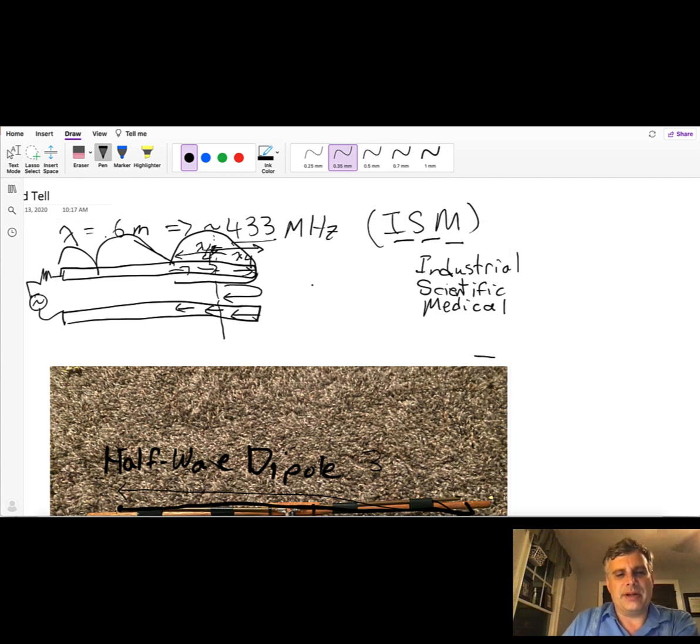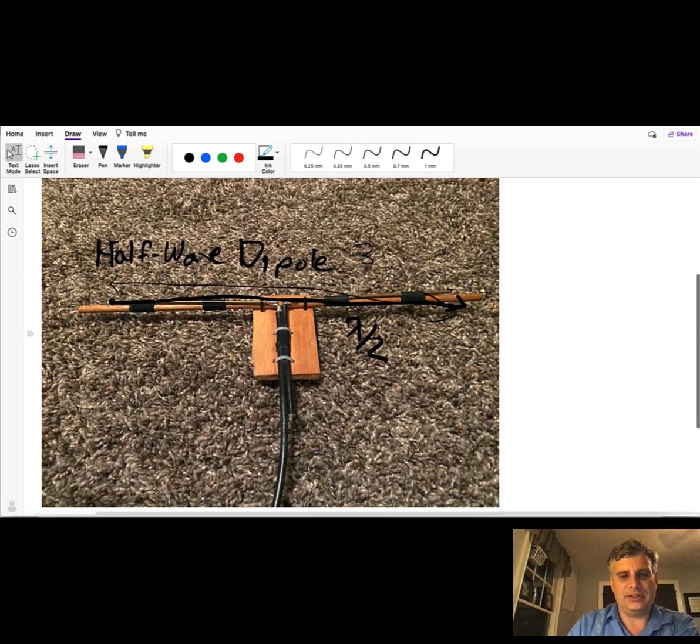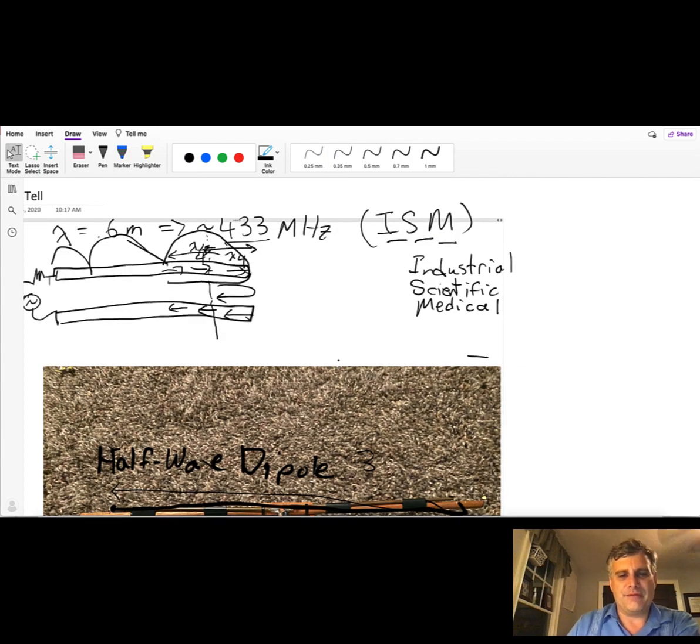And what's interesting about this is that you can use it to estimate what this half-wave dipole is doing in terms of standing wave currents, because it turns out if you wanted to solve this as a class 3 problem, one way of doing that for a wire antenna is to solve some complicated system called Pocklington's integral equation. We're actually going to talk about this later in the class.